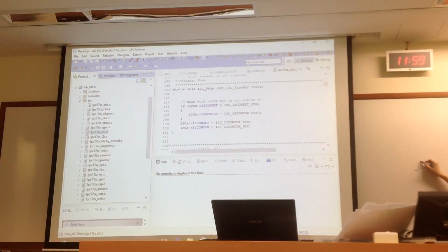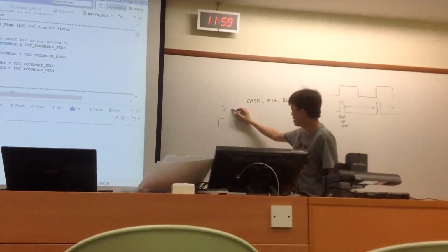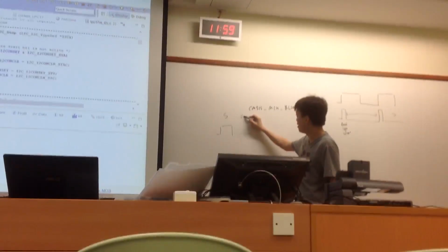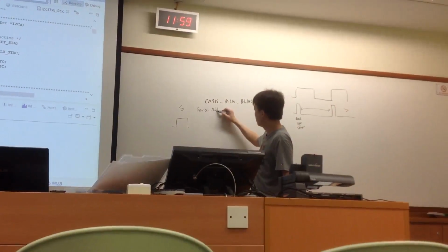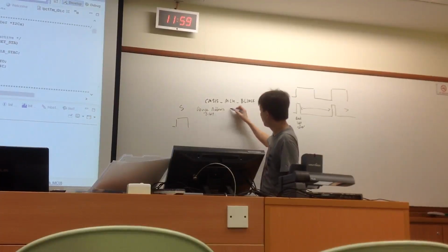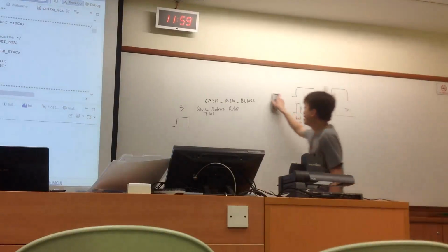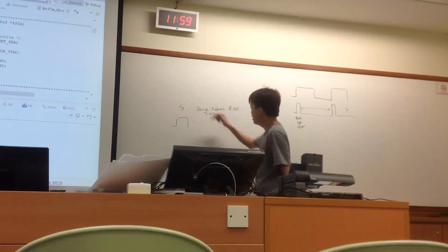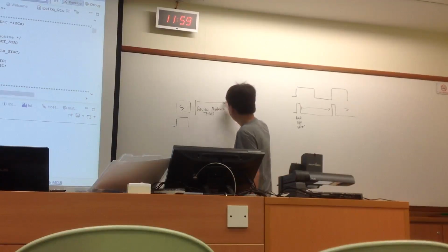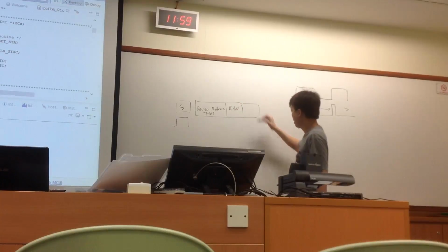First you send a start, then after that followed by the device address, 7 bit. Then followed by read or write, so the total is 8 bit. This is the first message. Then next one is the acknowledgement.